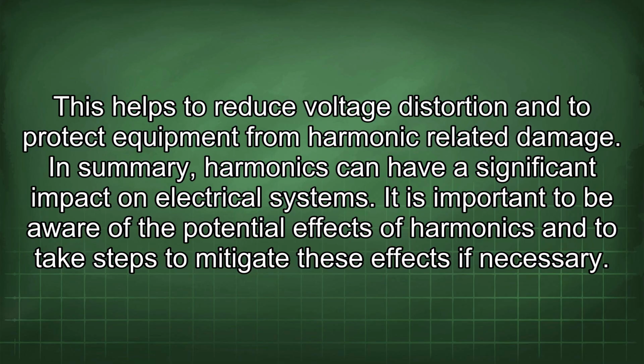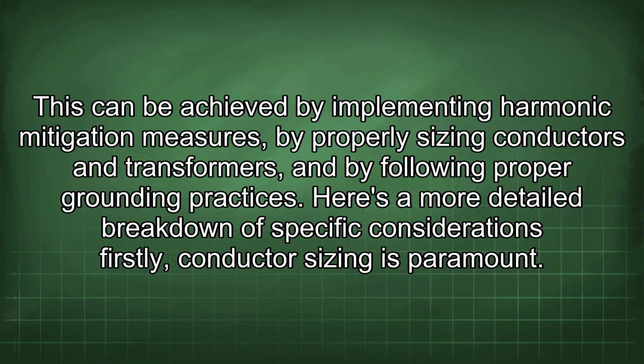In summary, harmonics can have a significant impact on electrical systems. It is important to be aware of the potential effects of harmonics and to take steps to mitigate these effects if necessary. This can be achieved by implementing harmonic mitigation measures, by properly sizing conductors and transformers, and by following proper grounding practices. Here's a more detailed breakdown of specific considerations.